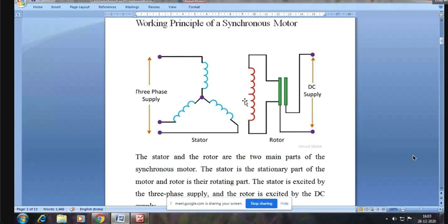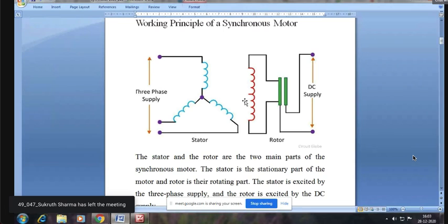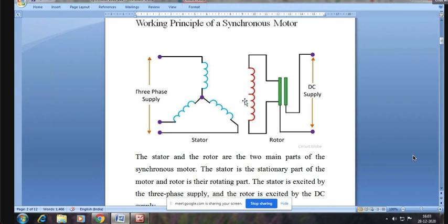Sir, I mean to say that the motor will not rotate in one direction continuously. Exactly. Good, correct. The motor will not rotate in one direction continuously. Otherwise, unidirectional torque is not established. For the motor to run in one direction continuously, unidirectional torque has to be established. That is not possible if we do not have the commutator segments and have only slip rings. And therefore, in the absence of the commutator segment or the split ring, the motor becomes what we call non-self-starting.